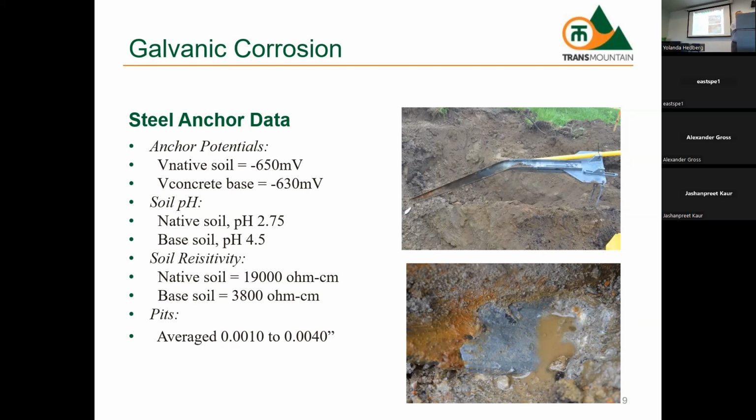Any questions? Was there some crevice as well between the concrete and the steel, and that was why it fell off there? No, there was an inch or two sticking out of the concrete, so it happened very close to the concrete. Because that was the closest spot to the copper that was already immersed in soil? No, it didn't have to do with the proximity to the copper. In a cathodic protection design, if I was trying to protect copper, this would be a perfect way to do it because there was a separation distance.